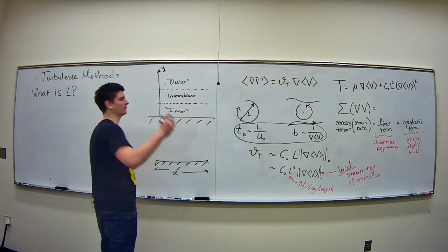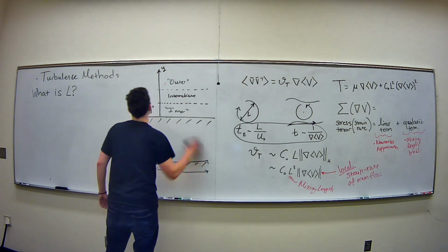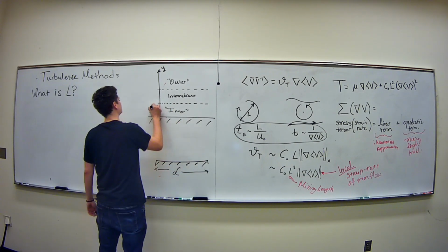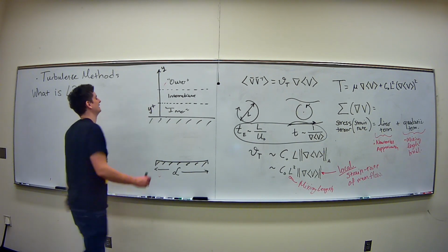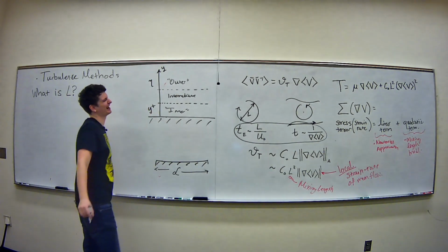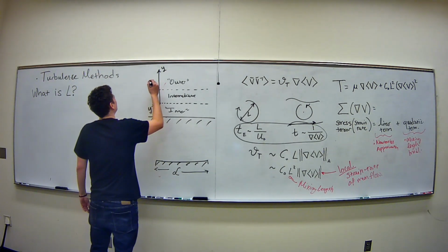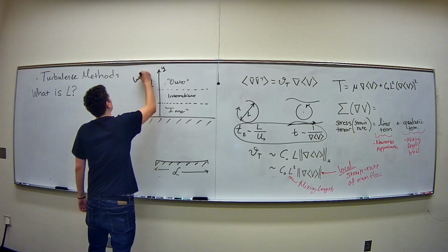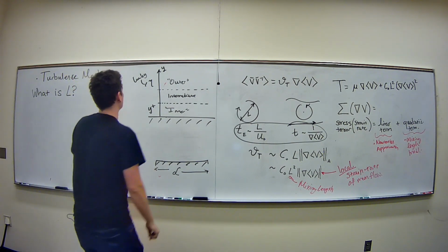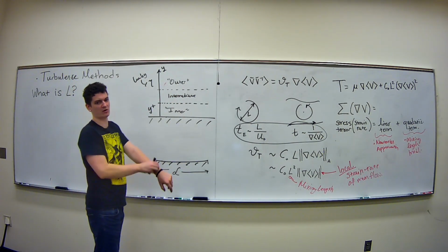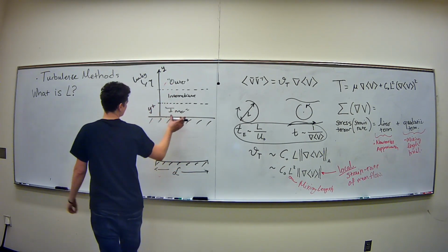So this is the idea of an inner variable of getting close to the wall. This one is called y plus, a non-dimensional variable that's close to the wall. And then in the outer, I believe we have eta. It changes from other books I've seen. Lumley uses eta. But the y plus is pretty synonymous in all literature, where in your turbulent theory over a wall or some flow close to walls, this y plus is usually referred to as the non-dimensional inner variable.